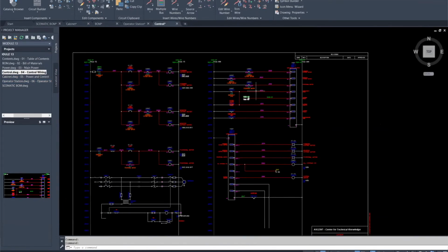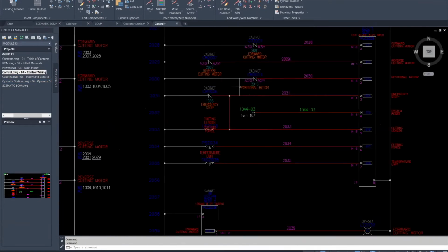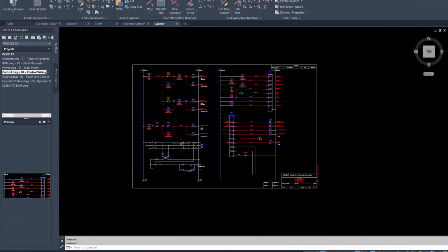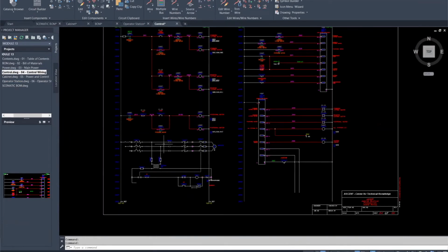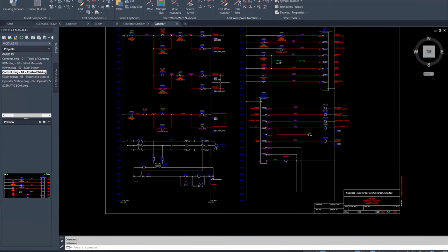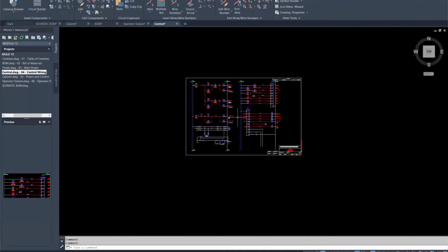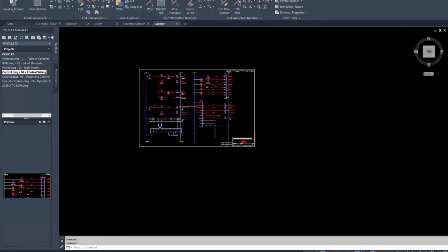So that's my schematic, and we added components, we erased components, we can build circuits, library components of circuits. It's very easy to build custom components. AutoCAD has a very extensive catalog, but I find many customers say, we use a special push button here that isn't in the catalog. So you build your own custom library components. And so after I have this schematic, then I can go out and build